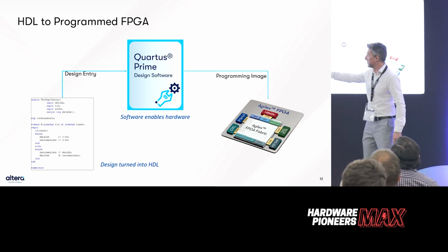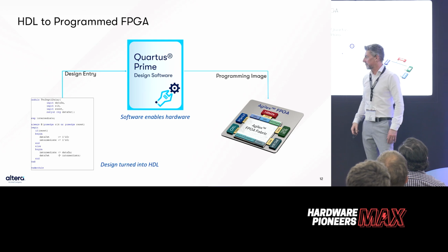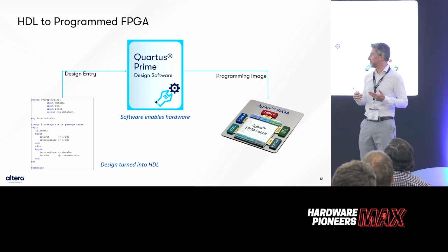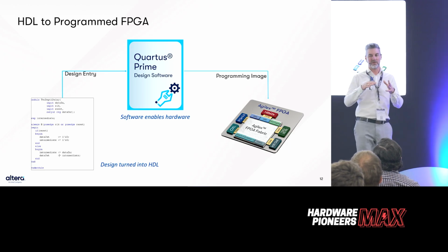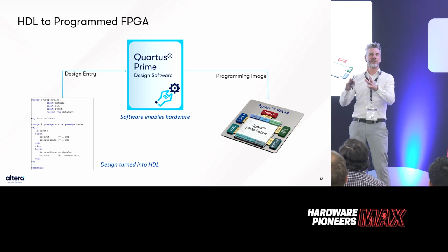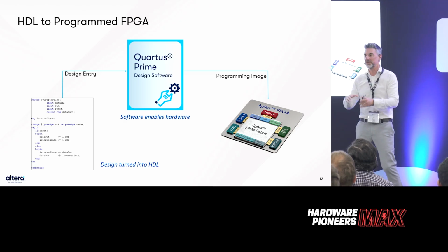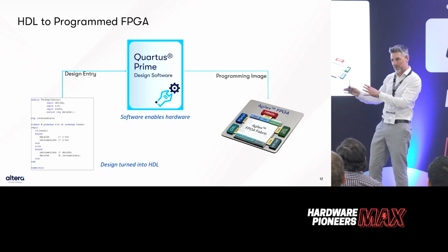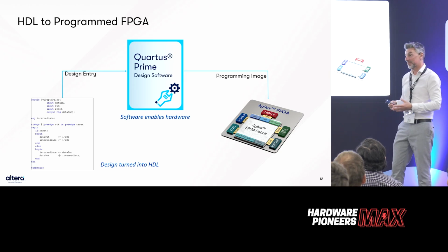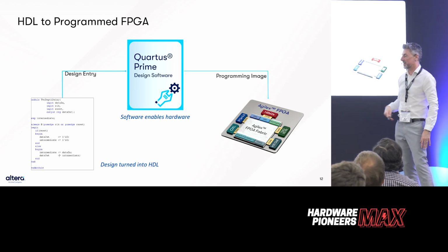It's very typed, and if you're not familiar with it, it's a very structured language, and if you're implementing FPGAs, you have to think a bit about the hardware. You're not just running a bit of software, you're thinking about, okay, I write this code, and it's going to turn out a bit like this in the device. There'll be some registers here, there might be a DSP block here, there's a bit of memory.